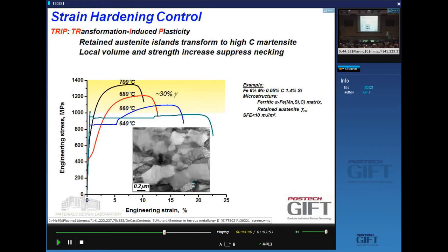So this looks very promising. The problem is you get very large localized deformation strains. Yes. Press forming people don't like this. Yes. And when you don't have localization, you get high strain rates, but very low elongations. So this is kind of material that looks nice but behaves badly. You get high strain hardening but low elongations.